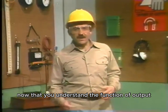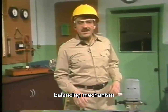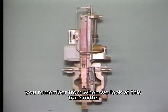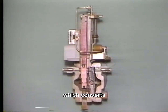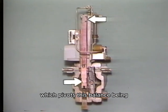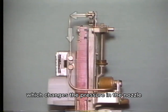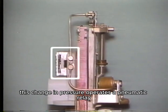Well, now that you understand the function of output or balancing mechanisms, let's take a minute to identify the output balancing mechanism in this differential pressure transmitter. Again, we'll use a cutaway to identify the internal parts. You'll remember from when we looked at this transmitter earlier that it has a diaphragm input mechanism which converts the difference between a high and low pressure into a mechanical motion which pivots this balance beam. The motion of this balance beam positions a flapper nozzle error detecting mechanism which changes the pressure in the nozzle back pressure compartment. This change in pressure operates a pneumatic relay.